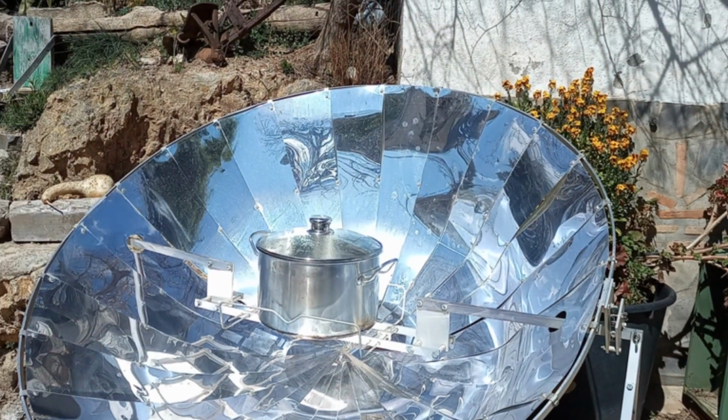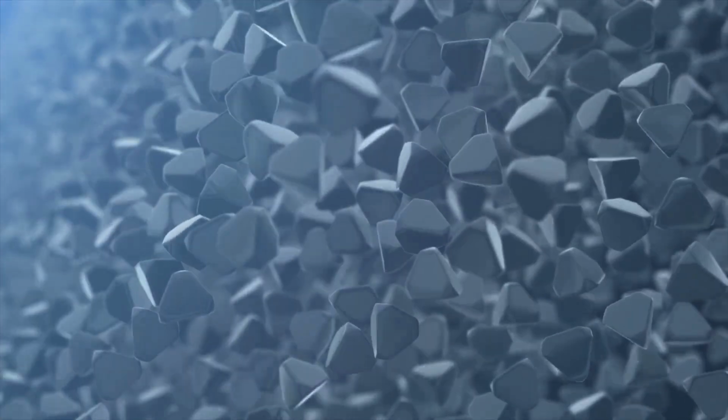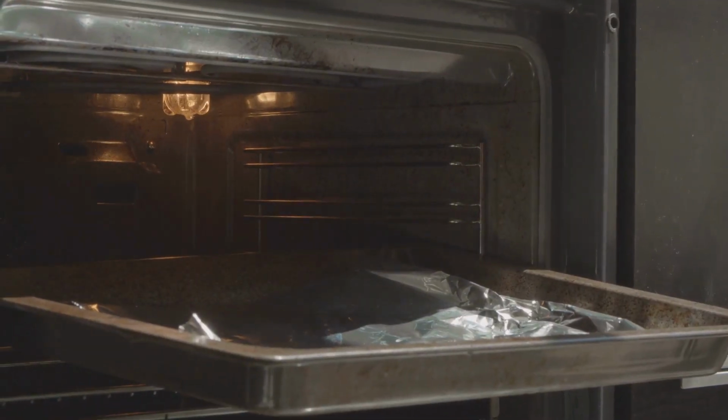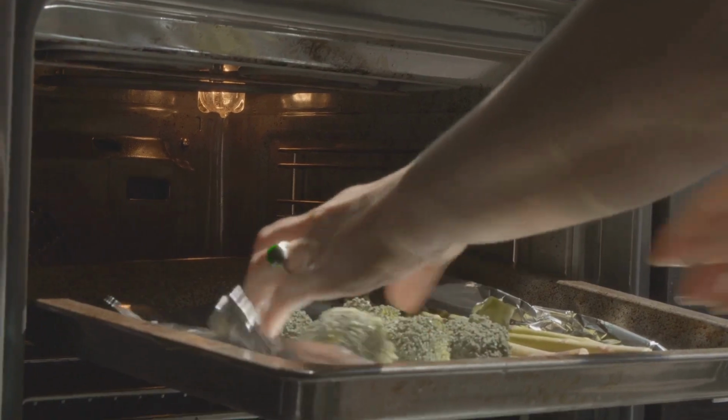Surface-to-Surface, S2S: a clear line of sight. The Surface-to-Surface, S2S model is like having a clear line of sight between objects exchanging radiation. It assumes that the medium between surfaces does not participate in the radiation process. This makes it computationally efficient, especially for enclosures with a large number of surfaces. Imagine a solar oven where sunlight streams in and heats the cooking chamber. The S2S model would be ideal here, as the air inside the oven doesn't significantly absorb or scatter the radiation.